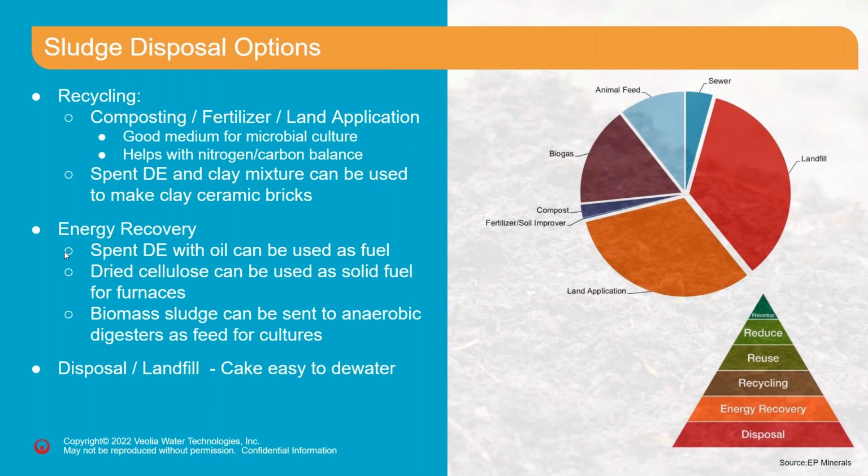Now, if you are sending the sludge for disposal or to the landfill, one advantage you have with sludge that has DE is DE can help dewater the sludge and reduce the volume and weight of the sludge before it is sent to landfill. And also, depending on each of the client's needs, we can look at identifying ways of reusing the sludge based on the geographical location and also the sludge characteristics.